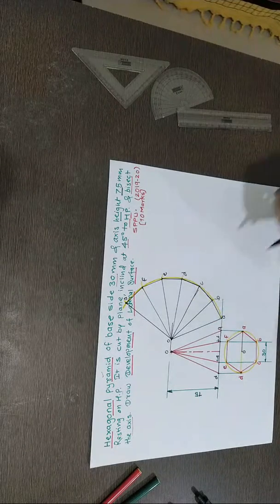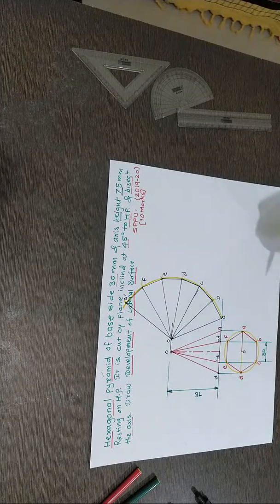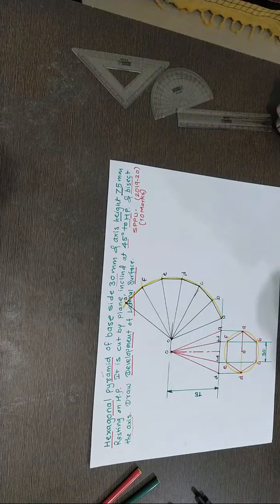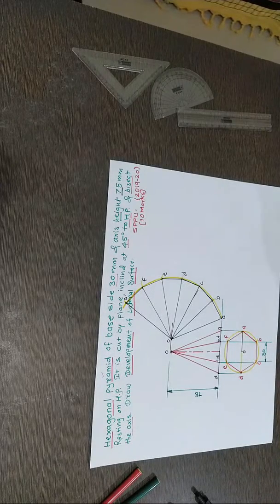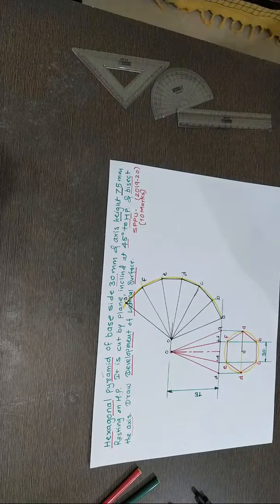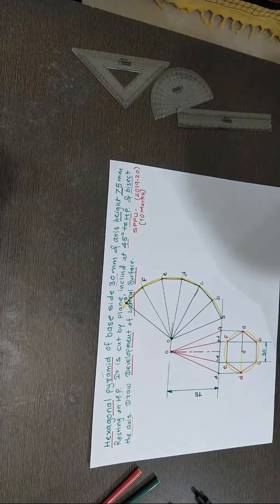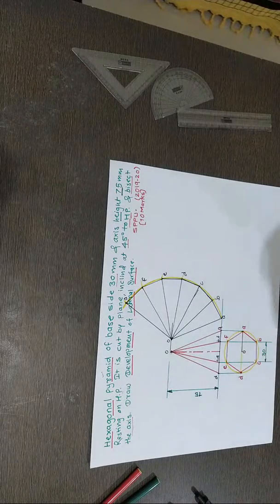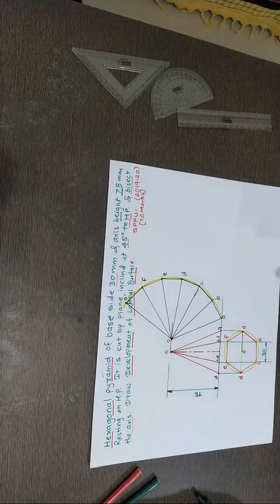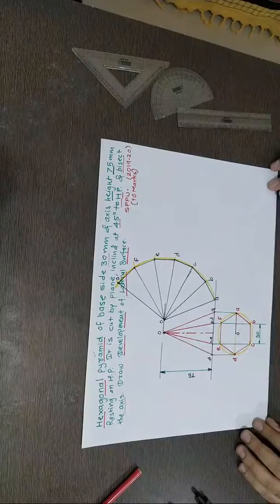So the black color lines you can see right now are the lateral surface you can see, to get that hexagonal pyramid. Now the next step is to locate the plane of the given condition. So how to locate the plane? Very simple: 45 degree to the HP, bisecting the axis. As a student of this subject, you know about these things. I hope it's visible.